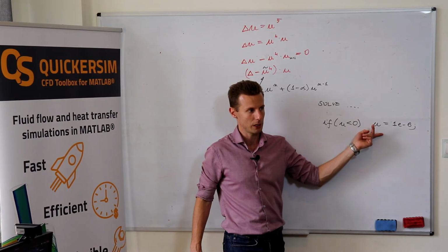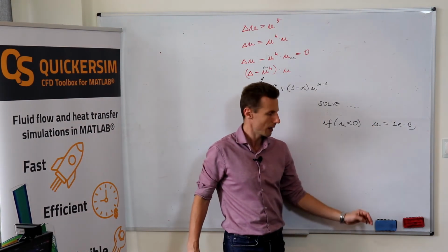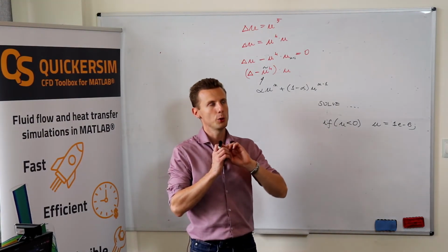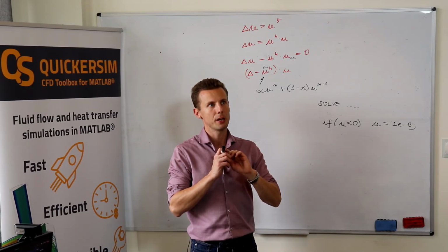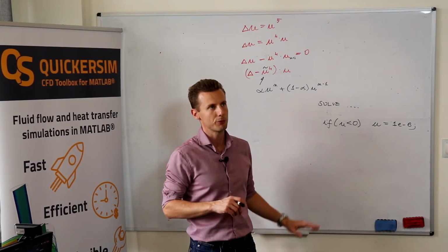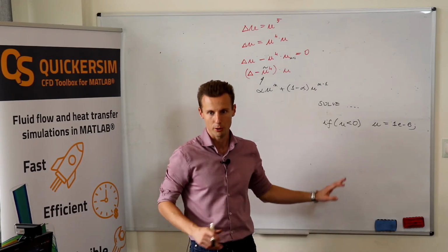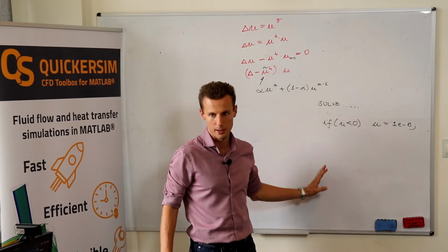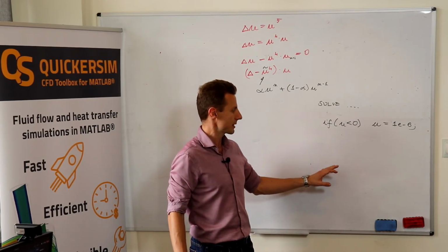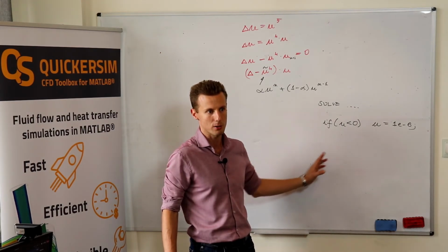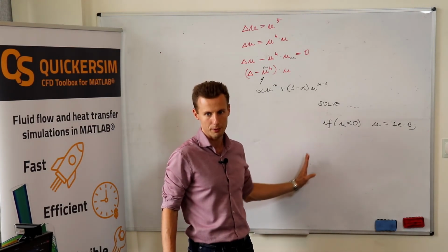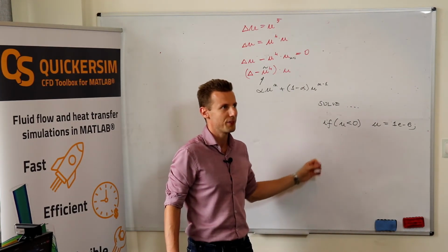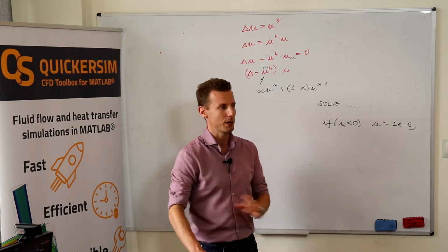I think there are much more elaborate flux limiters. We've been showing, for example, in the finite volume part of the course, how you calculate the flux between two different cells. We have given something that depends on the locations of the centroids, maybe on the values in one and the other cell. And then you use this flux calculation scheme.